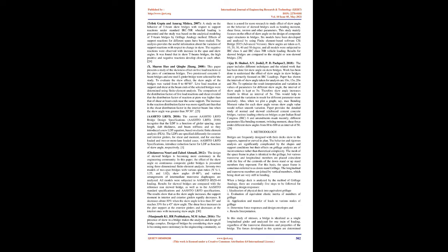4. Ebeido and Kennedy, 1996, investigated the influence of skew angle, as well as other design parameters, on the moment, shear, and reaction distribution factors of continuous, two-span, composite steel-concrete bridges and showed that the interior girders are more susceptible to a change in the skew angle than the exterior girders. They also concluded that bridge aspect ratio has an influence on the moment distribution factor. The effect of aspect ratio increases with increase in the skew angle.